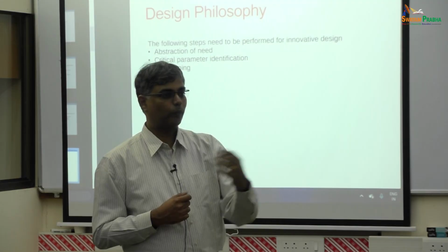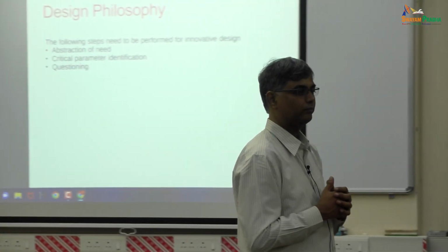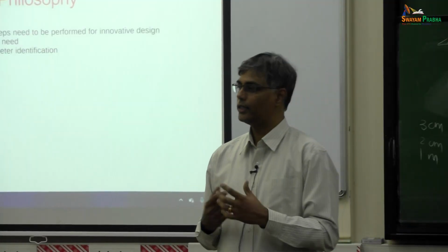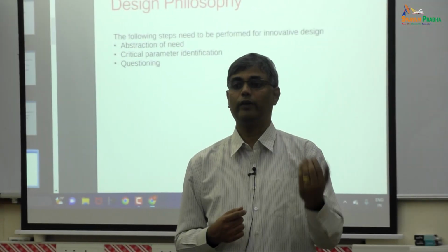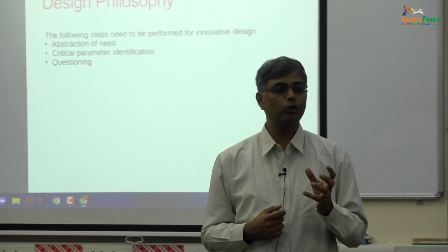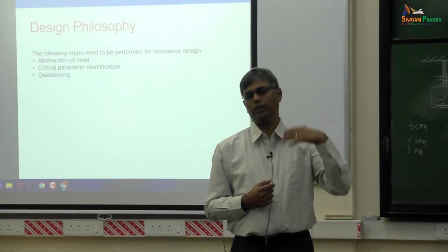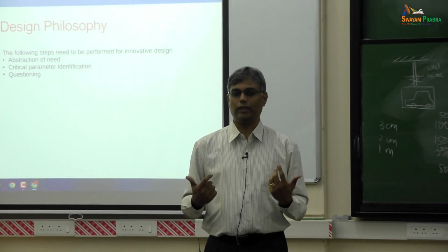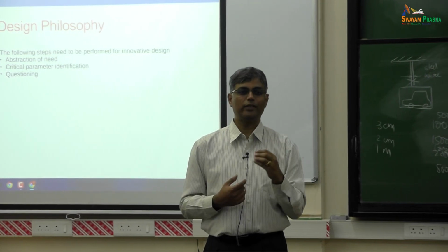Okay, so question? Yes, how exactly are we considering a bridge to be statically loaded? Because we have traffic going over it, especially in peak hours, it could increase a lot. Okay, his question is about the bridge, which I said is statically loaded, and he's worried about whether there's also a dynamic loading on the bridge. It's just the ratio of the static load to the dynamic load. The dynamic load component will be very small for these sort of structural objects compared to the static load.